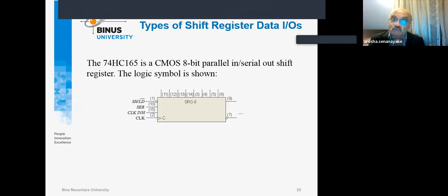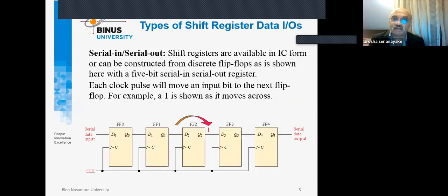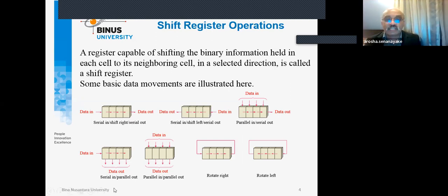So we can go back to understand what we are looking at: serial in and parallel out. You can see serial in, parallel out. Say the keyboard transmits 21H, how? 0001 first and then 0010 follows. 21, how do you write it in binary? 0001 and then 0010. That is how it transmits.